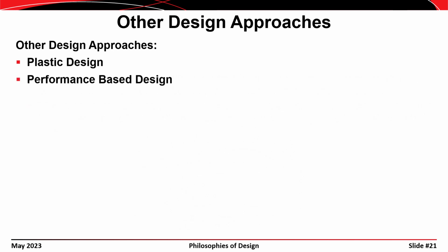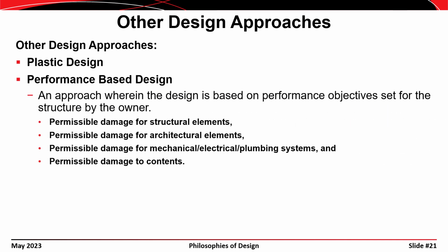Performance-based design is something that's just starting to come into vogue now. And the idea with performance-based design is that rather than going to a specification where it says that each member has to satisfy the sum of gamma q less than or equal to phi times r sub n, you go in and set different design criteria for the structure. Maybe as an owner, you would say that under an earthquake that has 5.5 on the Richter scale, I don't want any more than $400,000 worth of damage to my structure.